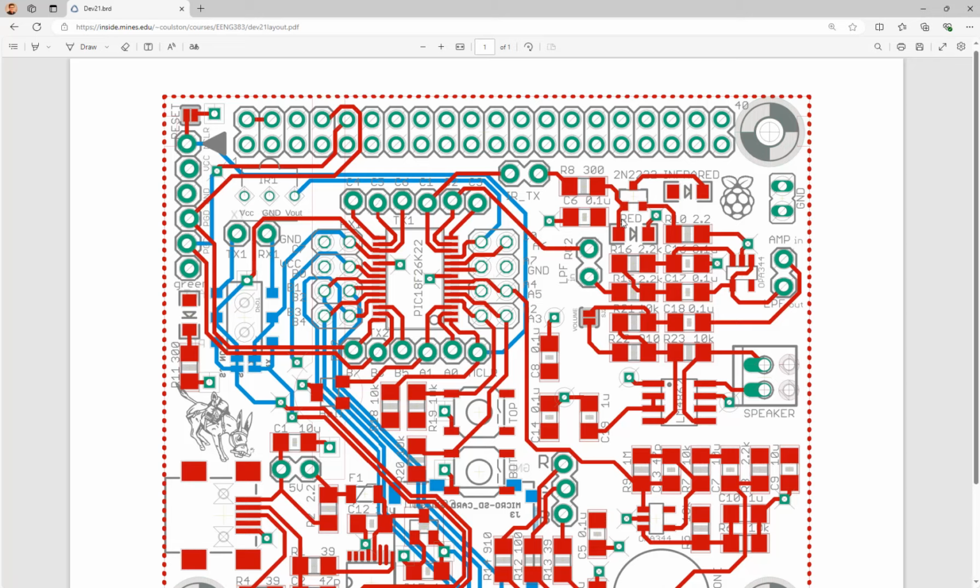You can find out if it's working by using a camera, but you have to turn off the ambient light in order to see it from the camera. Sometimes we don't really have to do it because you can always probe your microcontroller to see if you are sending out that pulse to drive that LED. You can probe it electrically.